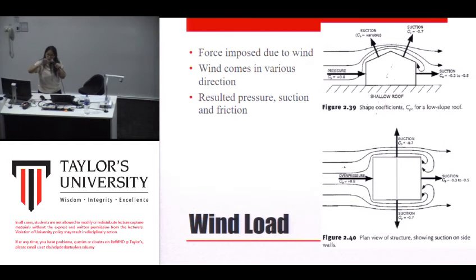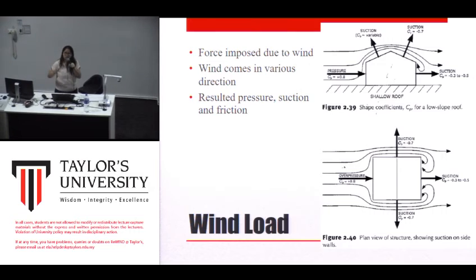The roof sheet is basically just bolted down to the purlin, just by using a standard detail. They never check. That's the reason why when strong wind comes, a lot of roofs tend to fly away.